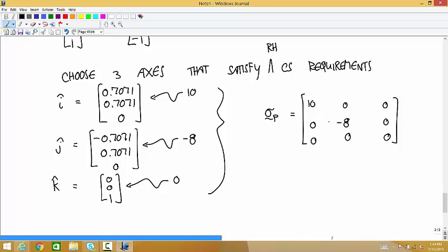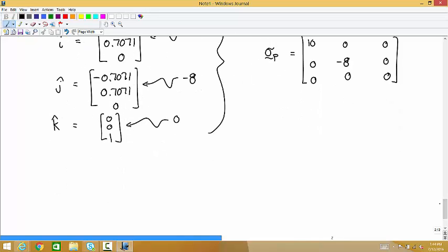These would have been in a different order in the coordinate system. And then when we do our rotation of 45 degrees to find the stress tensor with the maximum shear stress, we would have just rotated 45 degrees about a different one of those axes. We would have rotated about what we were calling the x-axis. Any questions about that? Okay, so then the rotation is the same to get the maximum shear.